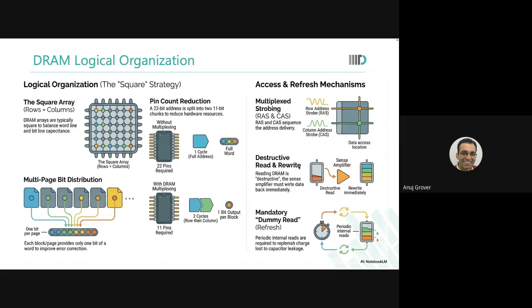If you were not to do that, then all the 4 bits would be of the same word. You would have to have huge area overhead for error correction. Now in DRAMs, the cells are smaller. What that means is that the same high energy particles which cause 4 flips in an SRAM can actually cause 16, 20, many more number of flips because the cells are closer together. So it's a physical phenomenon.